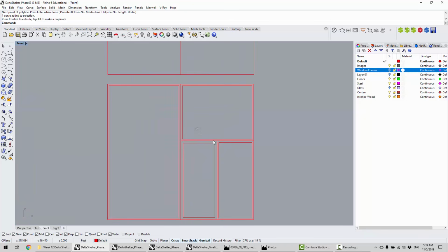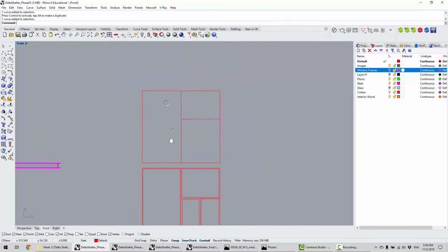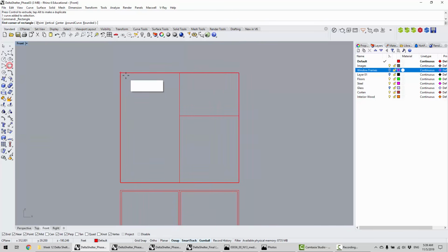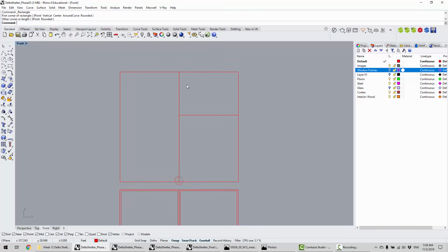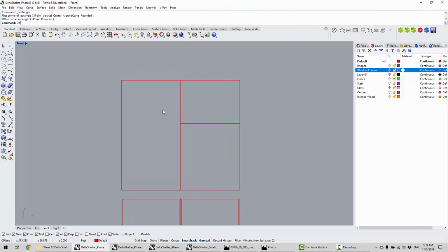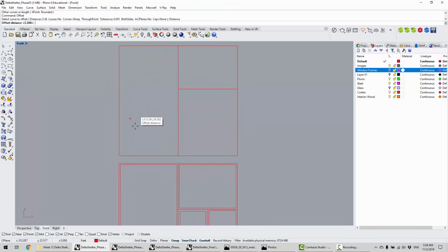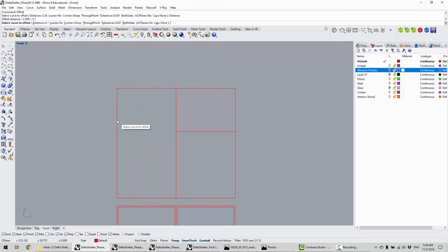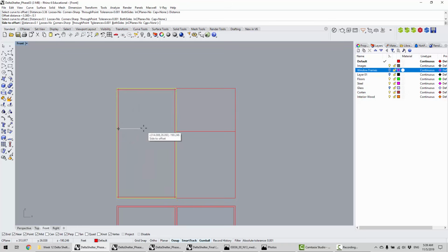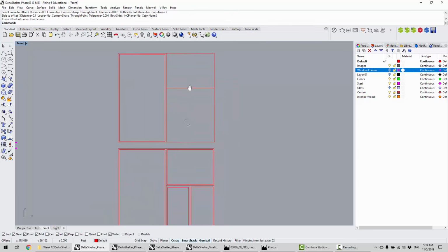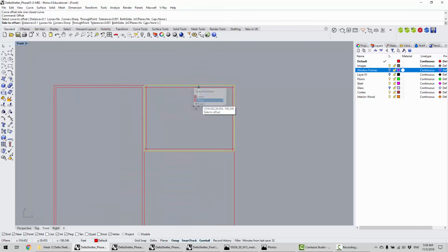You'll notice that there's one operable window where the thickness of the frame is slightly larger, right? So what I do here is use the rectangle command, and just trace over each section again, right? And using the offset command with a distance, I think for these skinny ones I did 0.1. So picking the right square, you can do these smaller ones just like that, okay?